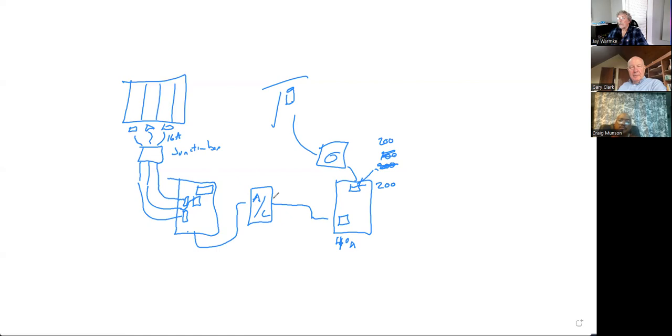Well, one alternative would be to do a supply side connection, which would mean instead of connecting in here, I would have to connect in somewhere between the meter and the main. To do that, you're going to have to hire an electrician to come out and disconnect yourself from the utility, and he's going to put a box or a splice in there somewhere. And AEP will be involved. Yeah, and he's going to make that connection. That can be a royal pain in the butt.